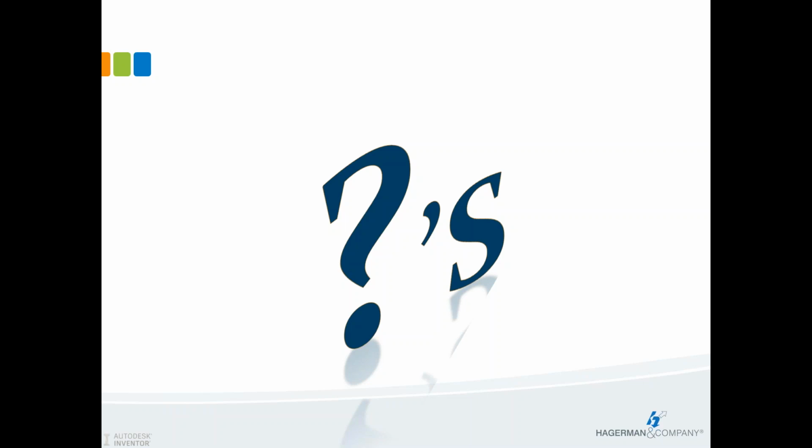There we go. Rick is asking, if you insert a JPEG, can it be grounded in place? If you are inserting it into a sketch, you can lock the endpoints of the sketch, the constraints. You can constrain it to projected geometry. If you're putting it in as a decal, it should go in based off where you're going to place it, and you can adjust that as well using the endpoints of that image. Should be able to.